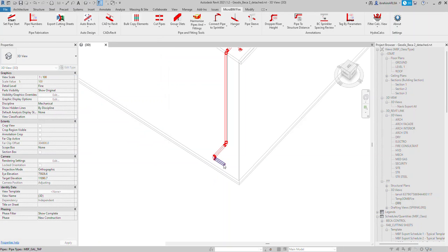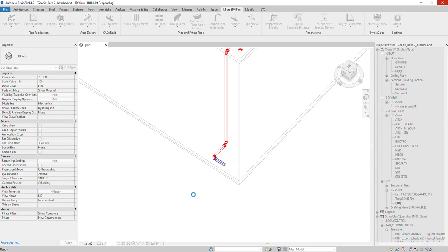Click OK and then click on the beginning of the network. And just wait for the tool to do the cutting for you. The best thing in the cutting tool is that it knows where the intersections are, so it doesn't cut at the intersection, which is wrong. And also it keeps the connection after cutting, and it obeys or restricts to the maximum cut length you set forth in the dialog.